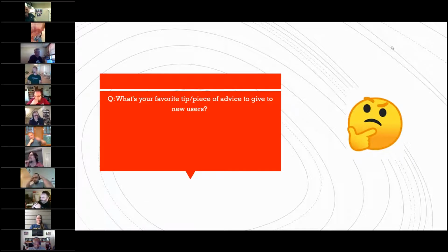There's a new one that's only a year or two old. If you hit Alt on a face when you're mating, it'll hide that face until you're done mating. But just that face. So if you've got a hole in a surface, you can hide the surface and get to the cylindrical face of the hole.